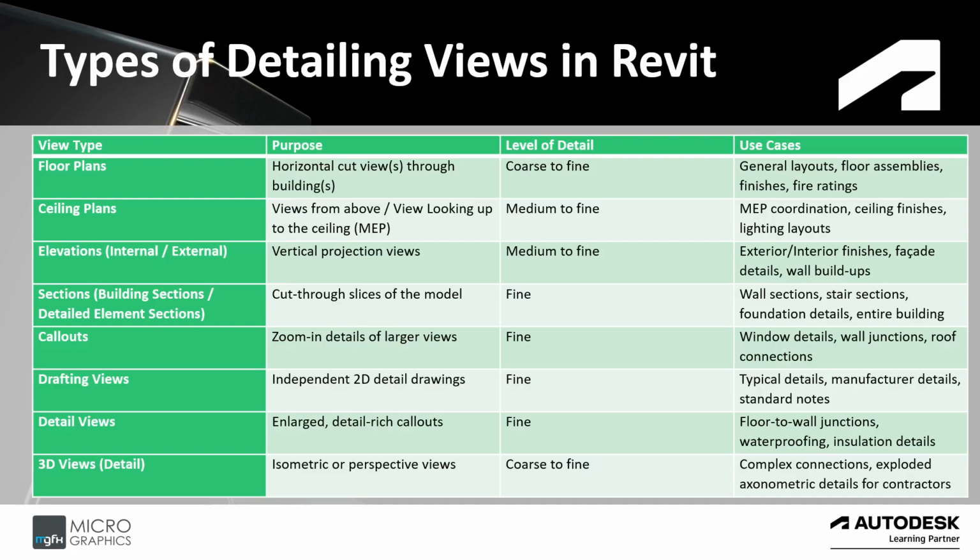So the types of detailing views in Revit would include floor plans. The purpose is horizontal cut views through the building or buildings, with levels of detail from coarse to fine. The use cases would be general layouts, floor assembly finishes, and fire ratings.